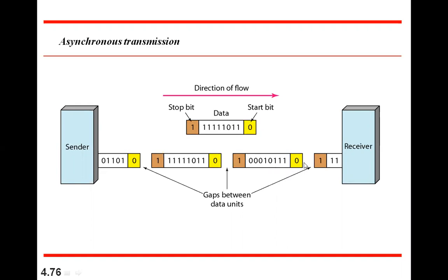That's why the receiver should be able to detect when the stream is starting, so the start pulse, or start bit, is required. Then after that comes this many bits. Of course, this is fixed, how many data bits we are sending. Similarly, it will be followed by a stop bit. That's how the receiver can detect all the bits from the received bits.